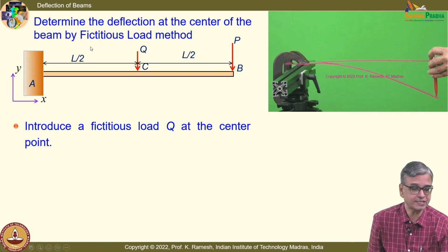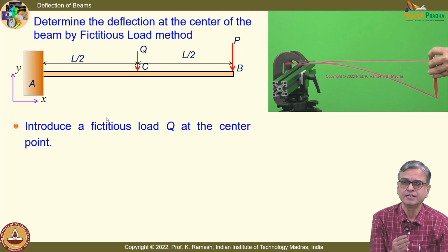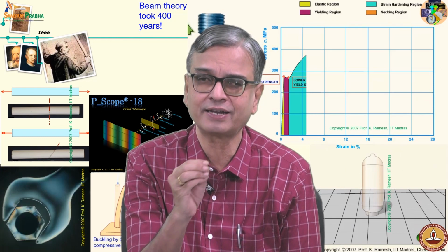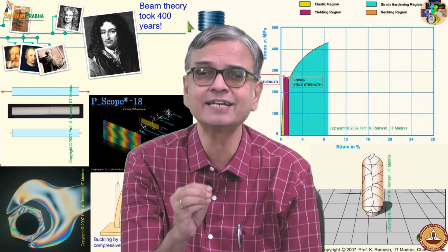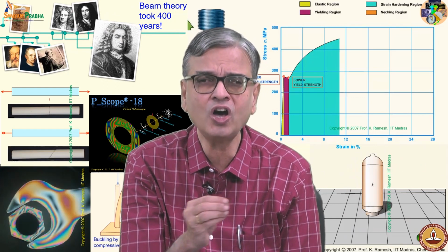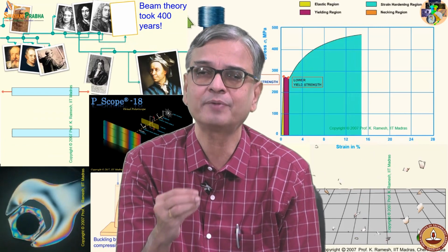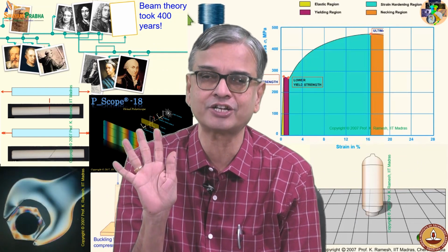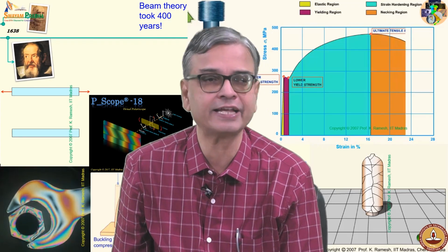So I have two sections. I have one section here, I have another section here. So I have to find out the bending moment in these two sections. From now onwards, we will not worry about the shear deformation. We have already seen how to incorporate shear deformation, and we have also seen shear deformation leads to small changes in the final deflection. Since they are very small, from an engineering perspective and engineering analysis, we can live with moment curvature relation. Fine. So we will confine ourselves only to bending energy.